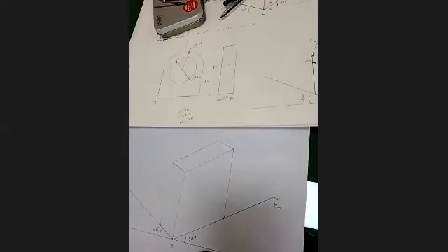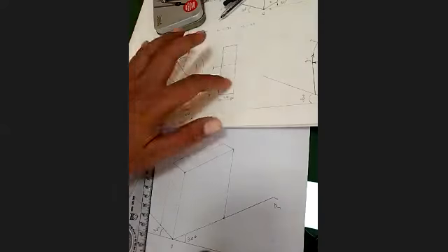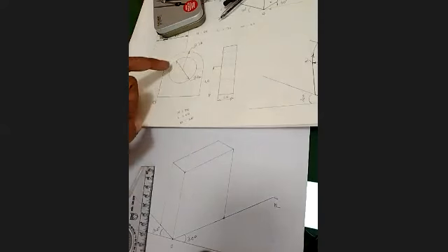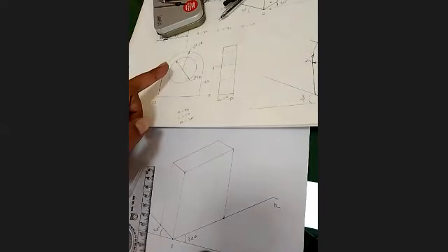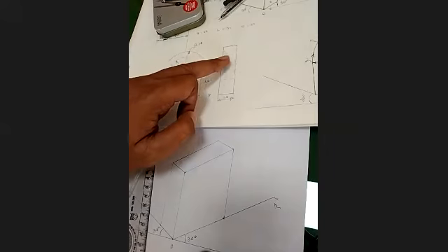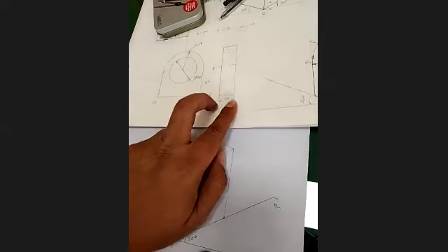I hope you are ready with this. Yes, are you ready? Yes, sir. Okay, once the box is ready, you have to look at the front view and the side view. In the front view, there is a circle and a semicircle. Corresponding to this circle, in the side view there is a dotted line, which means there is a through hole for the 20 millimeter width.